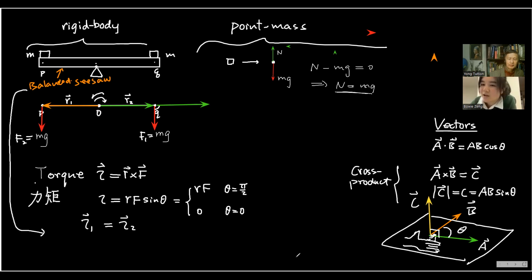So in this case, the torque is coming towards us, right? No, into the page. At this moment, F1 is into the page. The torque is into the page, because these are R2. Do you agree? So if you use your right hand, four fingers toward the direction of R2 and curl into the direction of the force F1, the thumb will give a direction into the page.